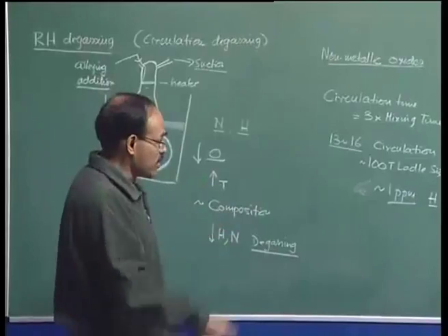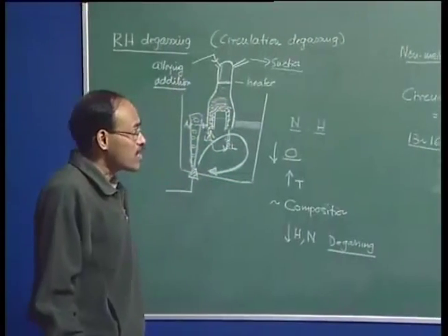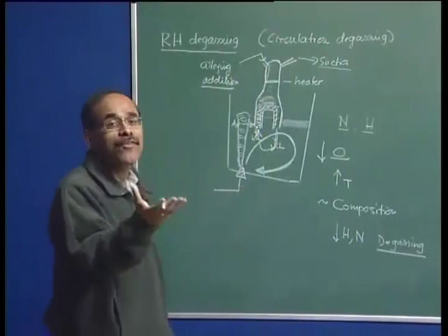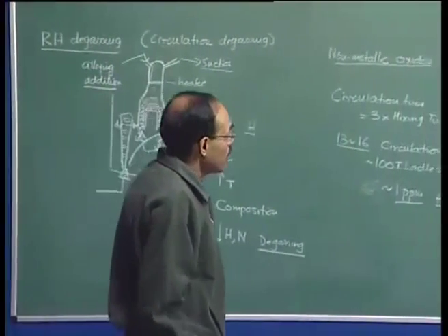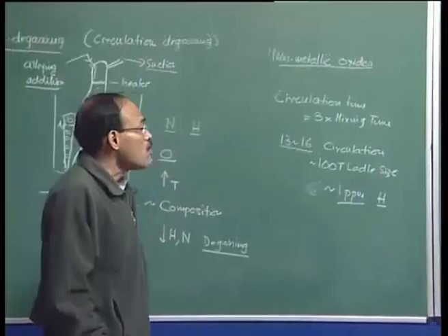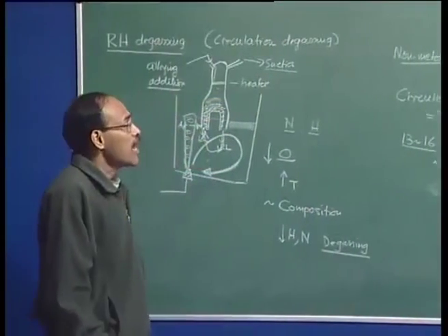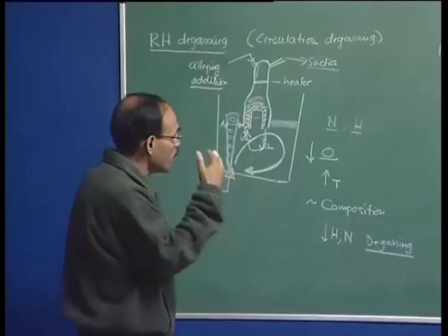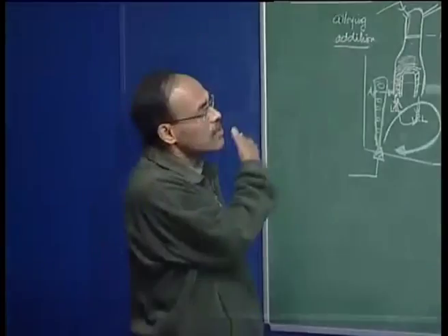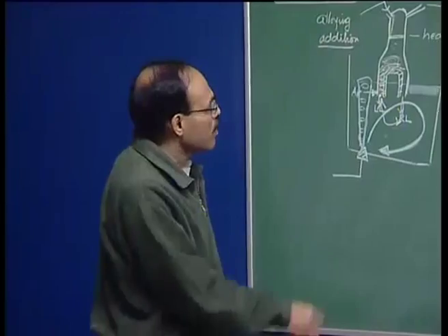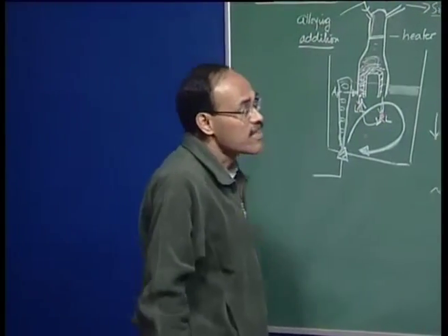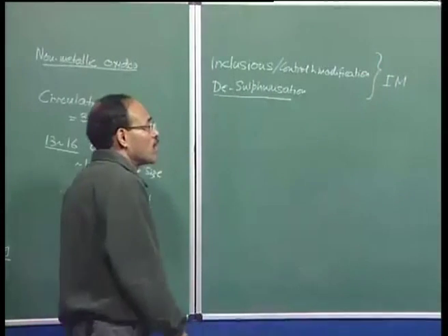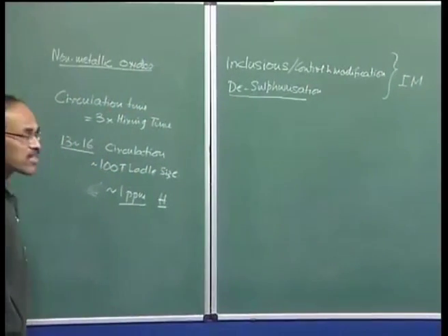Liquids have a greater tendency to coagulate or coalesce, and if they can become bigger, they can really rise up to the slag metal interface very easily. So, modifications of inclusions and desulfurization may be necessary in some processes beyond conventional ladle metallurgy treatments, ladle furnace and vacuum degassing techniques. And there we have a host of techniques, particularly injection metallurgy, where we inject certain materials.